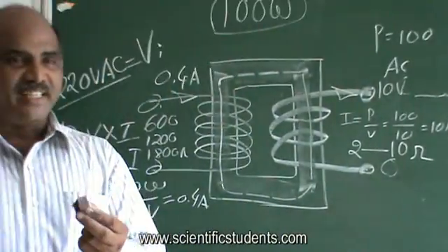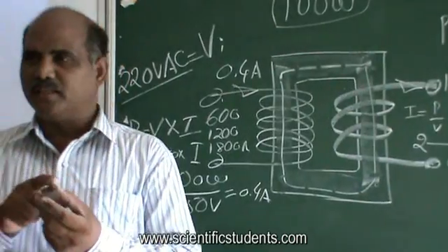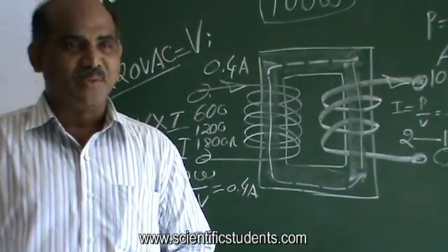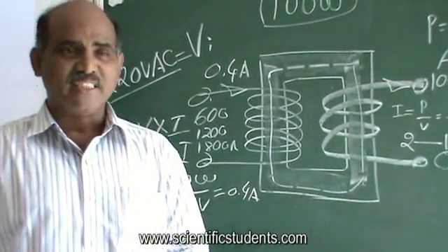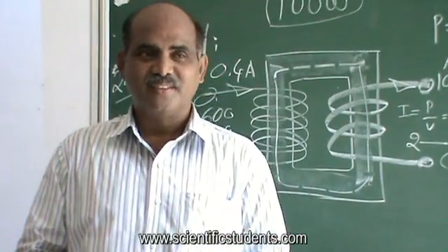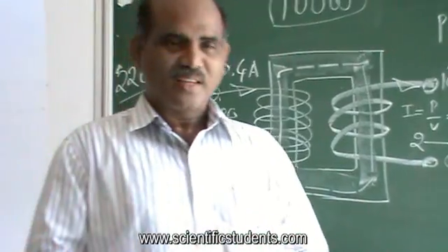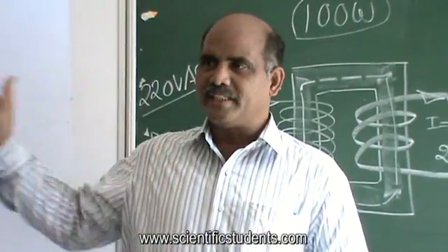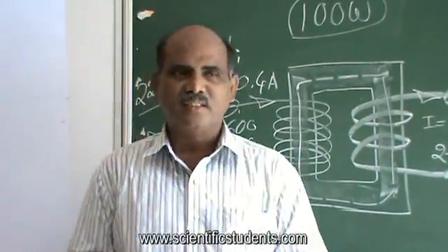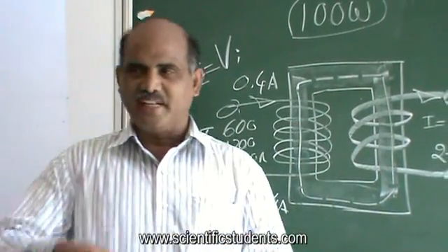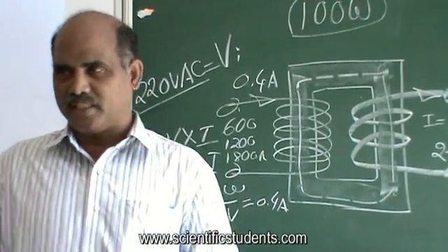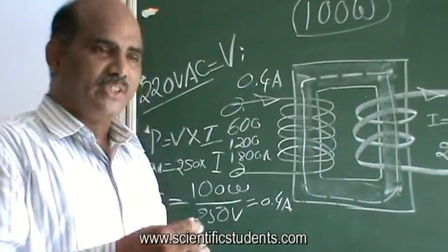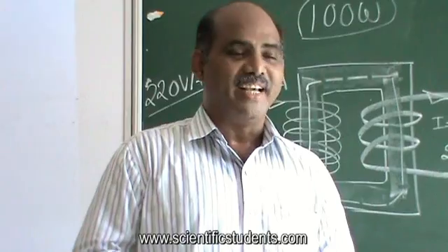So if you measure the resistance of these two coils, and one is showing in the order of hundreds of ohms and the other only a few tens of ohms, then which is secondary and which is primary? Tell me fast. The one with more resistance is primary and the one with less is secondary. Now, will you connect 220 volts AC incoming to the primary or secondary? To the primary. From the secondary you can take out. Now you understand how to convert high voltage to low voltage, AC of course, not DC. Now we shall discuss for the next 5 minutes converting AC to DC.